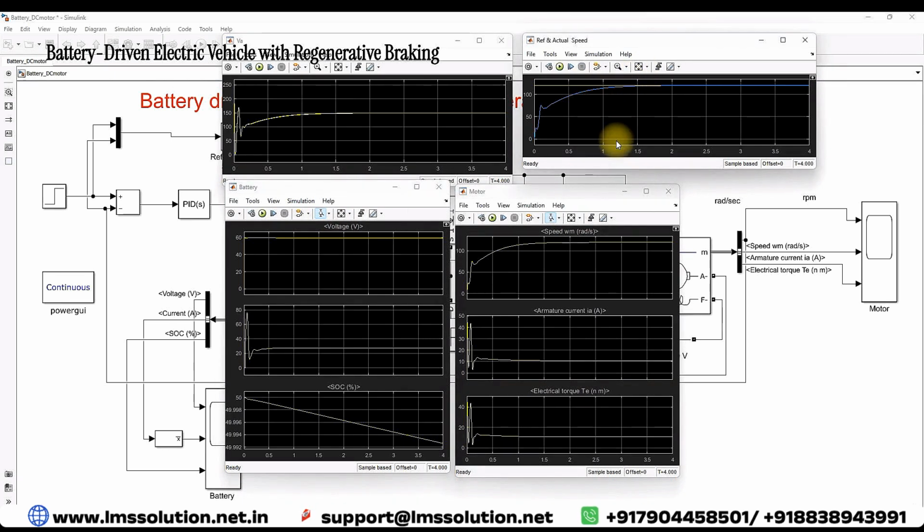That means we are going to apply the brake here in order to create the regeneration concept. So first I am going to maintain the reference speed equal to 120 radian per second. After some seconds I am going to change the speed from 120 radian per second to around 50 radian per second, and then we have to check the changes in the system, how the machine will react when we apply the brake.